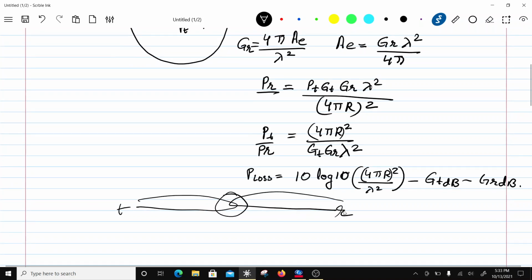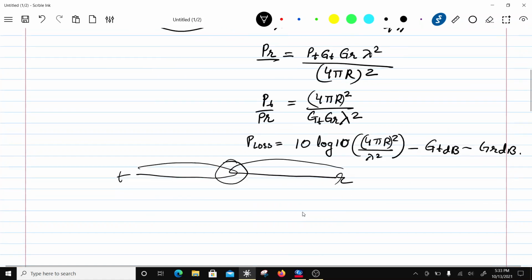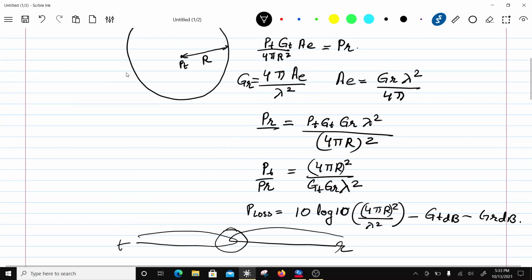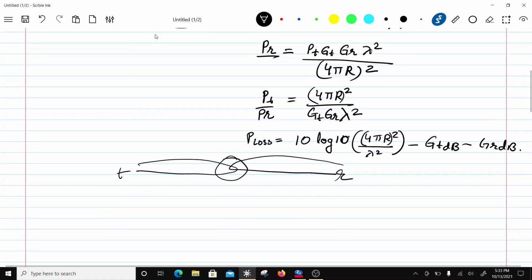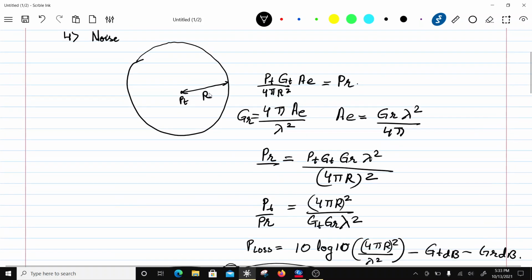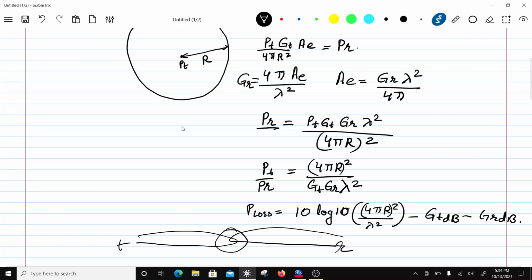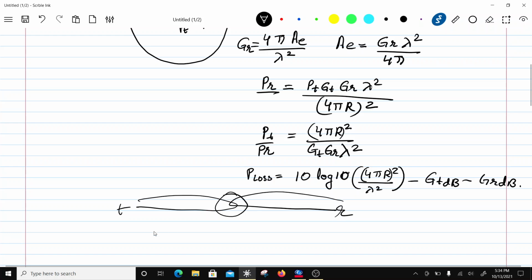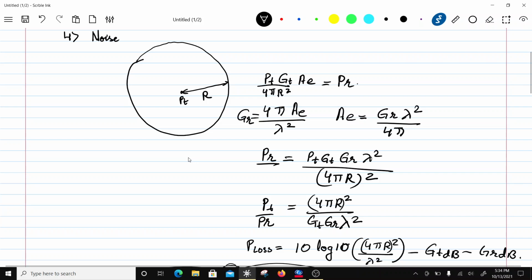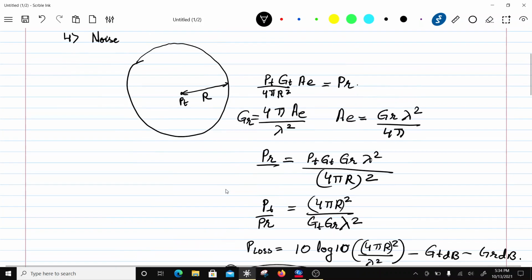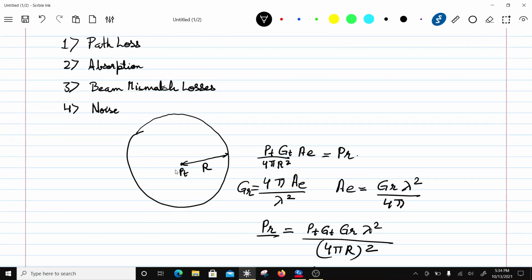And fading is also not always there, it changes with time, right? Especially when the channel is not stationary. By stationary, I mean the channel characteristics do not change over time. If they don't change over time, it's a stationary channel. If they do, then it's a non-stationary channel, right? So those issues will come in. And second, if the transmitter and receiver are mobile, not fixed point, then this scenario is more common. So multipath fading and channel distortions would come in, right?